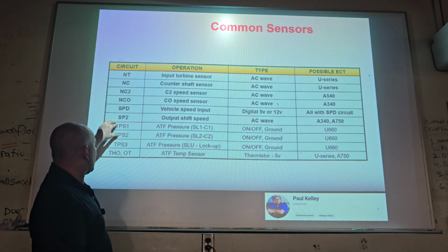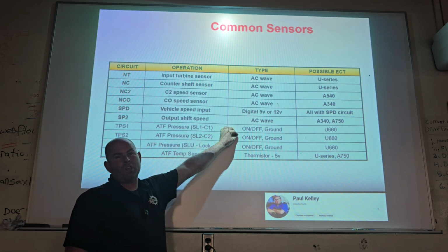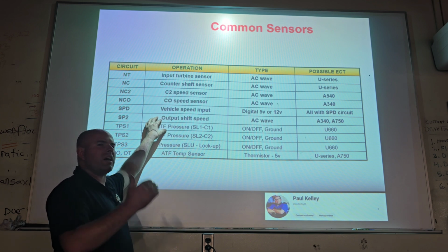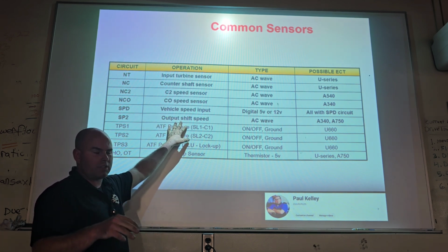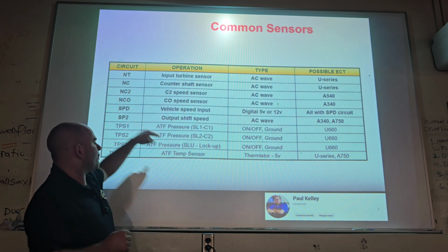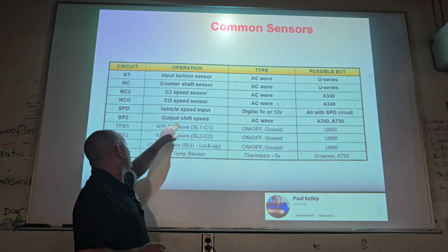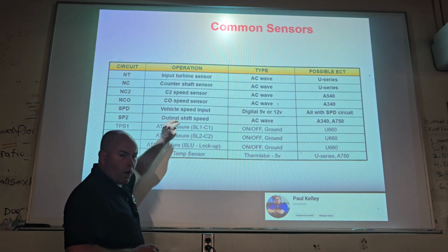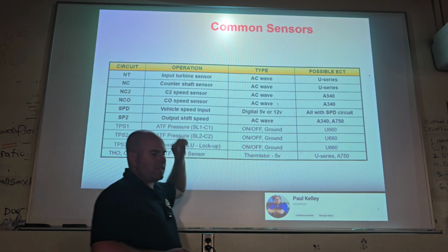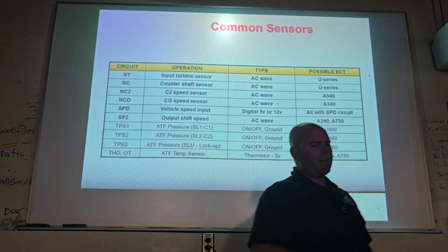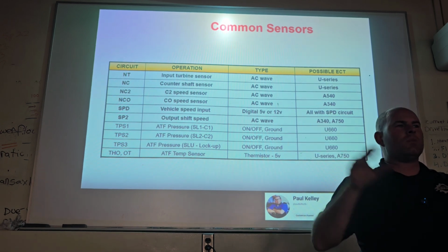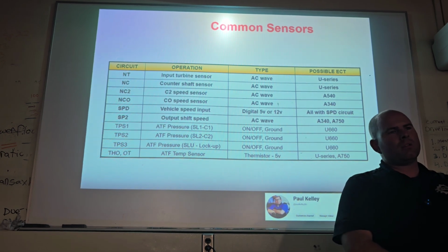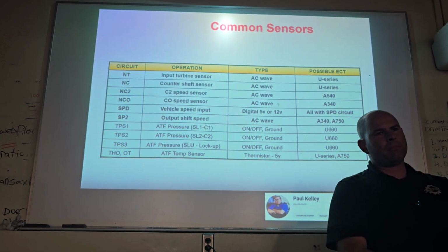So to me, this is the ideal diagnosis, when you have a pressure sensor that verifies the operation of your shift solenoid and that your clutch is engaged. Amazing. If you were to look at pressure sensor 1 and you were to see 140 PSI, which is your line pressure, you could look up line pressure is 140, C1 is 140, and it's slipping. What's the cause of the slip?